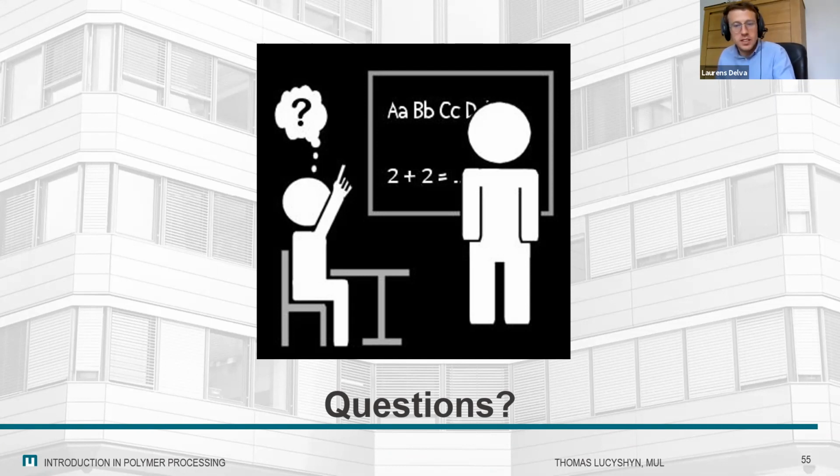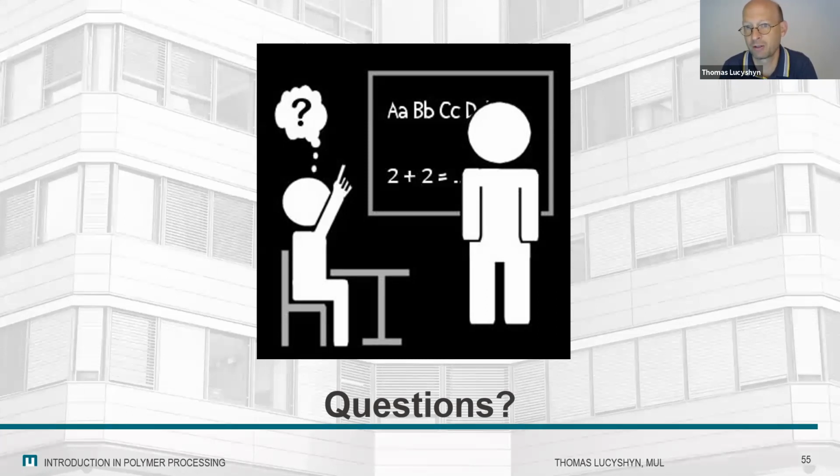She says that in the beginning you made a distinction between elastomers and thermoplastics. What about the reprocessing or the recycling of thermoplastic elastomers? So which is a special case, of course. Yeah, I would say thermoplastic elastomers are basically copolymers. So part of the chain is thermoplastic and part is elastomer. I'm not an expert, I must admit, so I'm not focusing on this and have not much experience on recycling of this, but I would say it should be possible to remelt them again, because the thermoplastic phase of this material is still able to remelt, and so it should be shapeable again. So I would expect that it should be possible to conventionally do mechanical recycling of that.